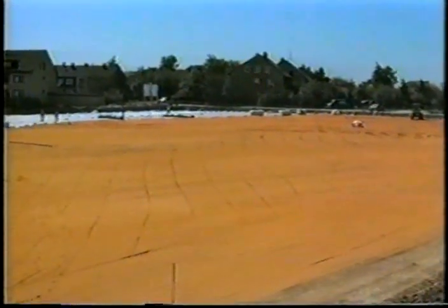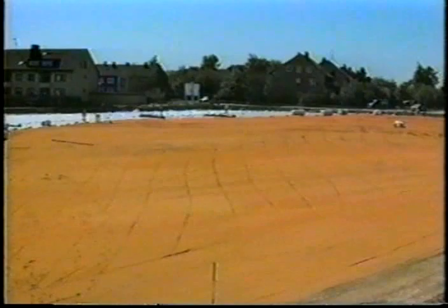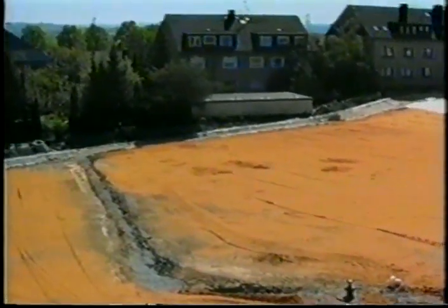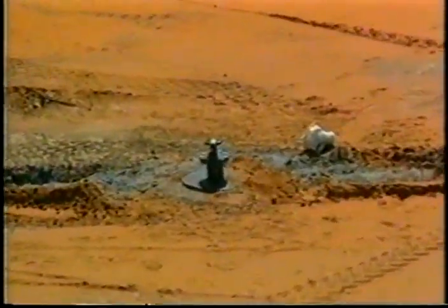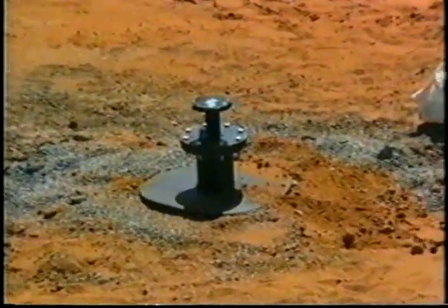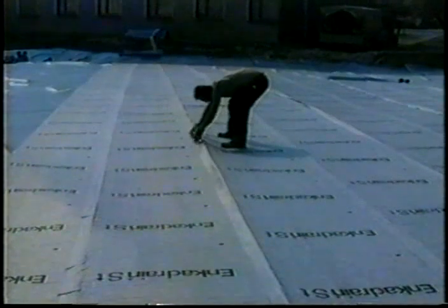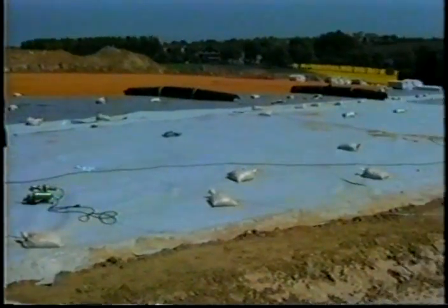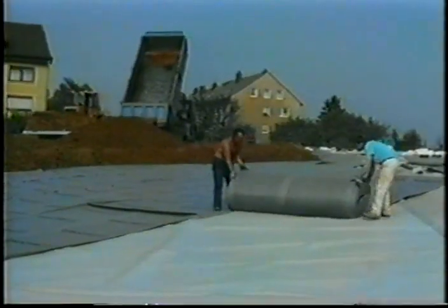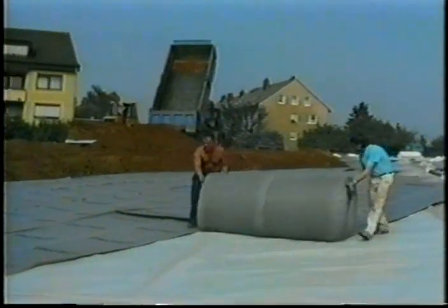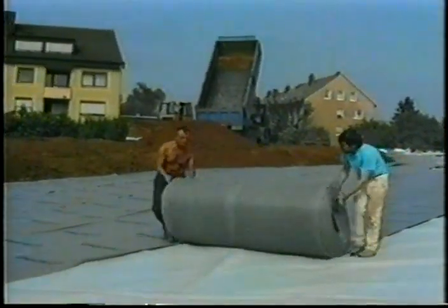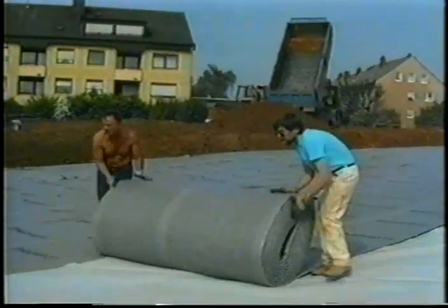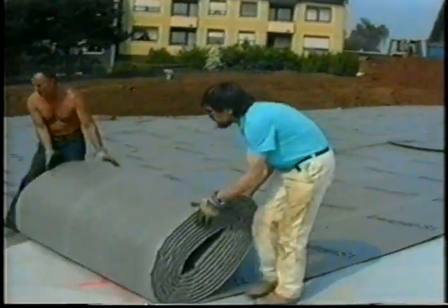The old cap was therefore replaced by a new one. The first layer of the landfill cover was sand, in which pipes were laid to carry the gas to a central evacuation point. Second came a layer of geocomposite to transmit rising gases, and above this a geomembrane liner. Another layer of geocomposite was placed above the geomembrane to channel away water from the soil above it. This was to ensure the stability of the cap.